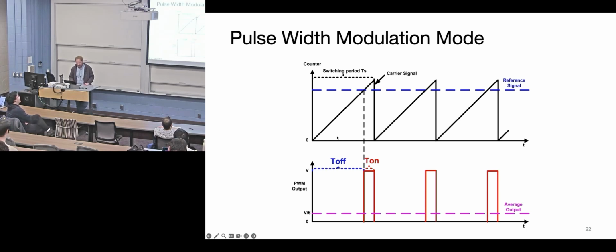It's important to know how to generate PWMs. So here in this case, we're going to set up some threshold value. And when you count up to that, your PWM will go high. And when you hit your auto reload, it's going to go down. And this way you can control the pulse widths of timing. What does duty cycle represent here? How do we calculate duty cycle?